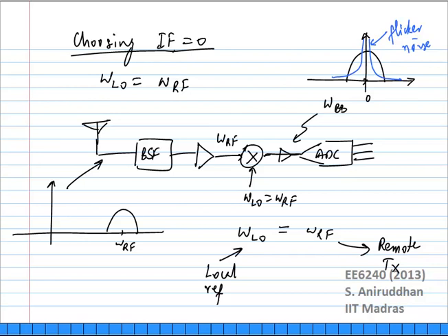Every amplifier, due to mismatch effects, will have a certain DC offset. The DC offset could be fixed or slowly time varying, right? A slowly time varying DC offset will have the same effect as flicker noise, because flicker noise is also at low enough frequencies. How do you solve the DC offset problem? Is DC offset a problem here? Naturally. Because then you lose some portion of the signal here. It's going to swamp out, because DC offset could be quite high actually, several tens of millivolts.